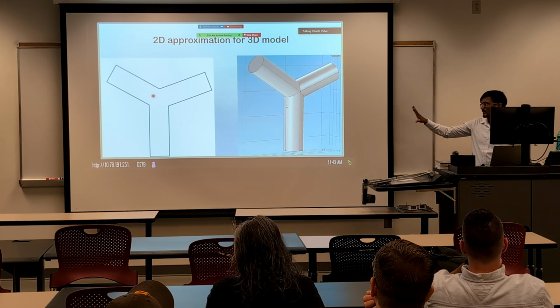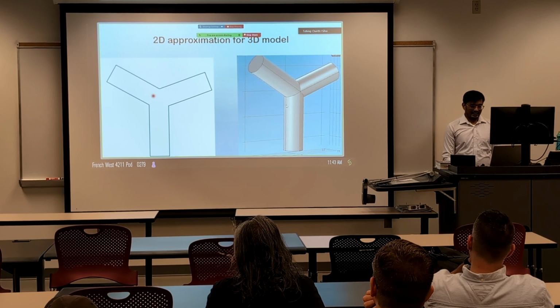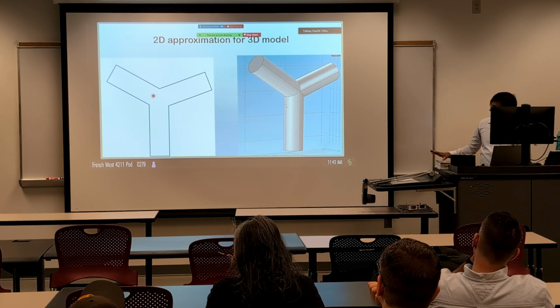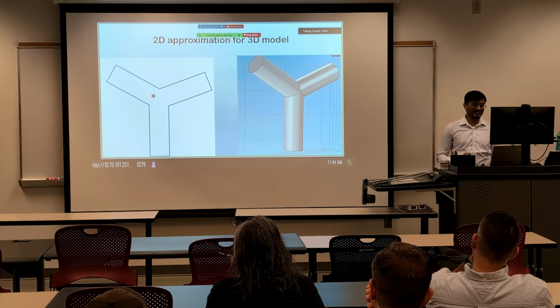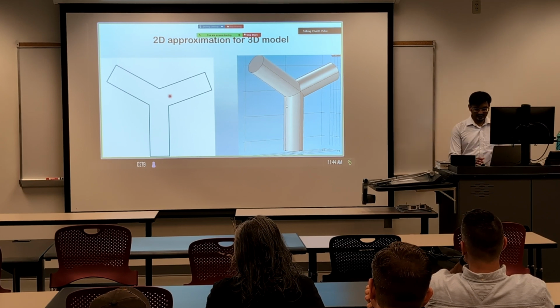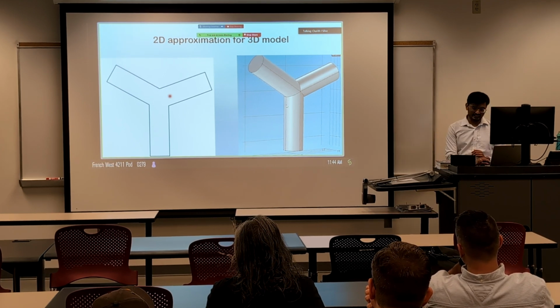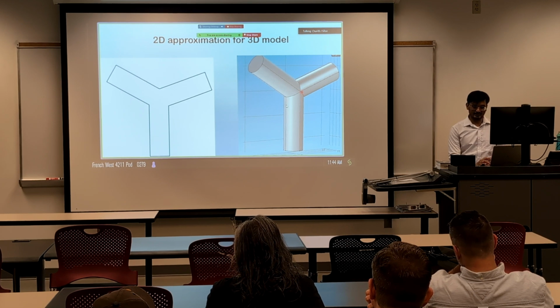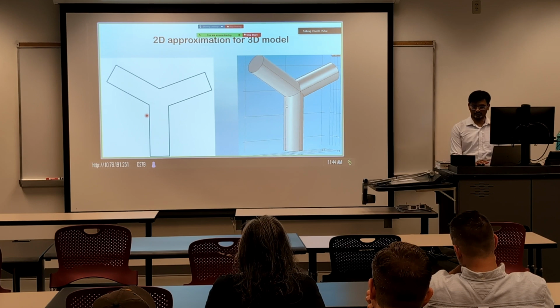Later on I will be improving this domain. Then we applied the same initial conditions to both and calculated the shear stress and the pressure values along the walls by solving the Navier-Stokes equation. We repeated this process by varying the angles in the 3D geometry, hence obtaining different patterns for the 2D geometry.